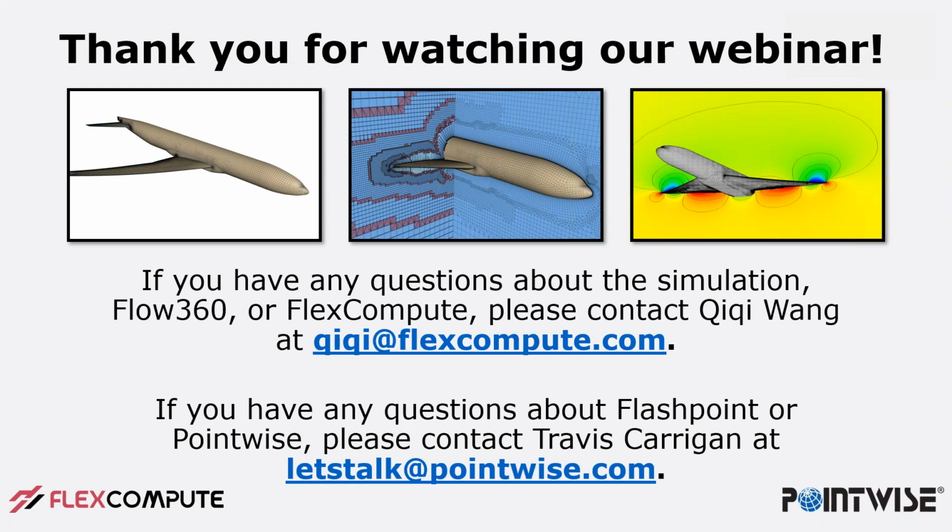Is the mesher parallel? We're talking unstructured here. Pointwise in general is multi-threaded. The unstructured surface mesher that is used by Flashpoint surface meshing is multi-threaded. The volume mesher currently is single-threaded.